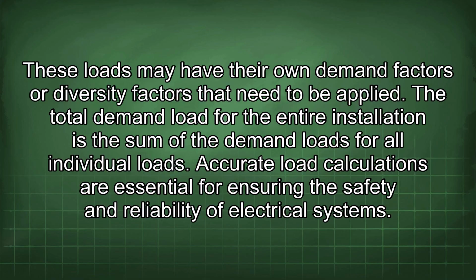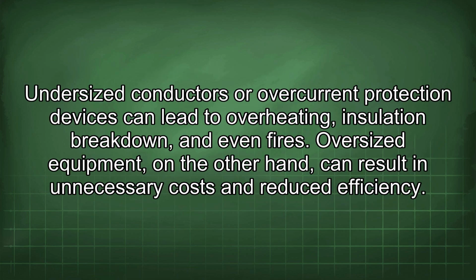Accurate load calculations are essential for ensuring the safety and reliability of electrical systems. Undersized conductors or overcurrent protection devices can lead to overheating, insulation breakdown, and even fires. Oversized equipment, on the other hand, can result in unnecessary costs and reduced efficiency.